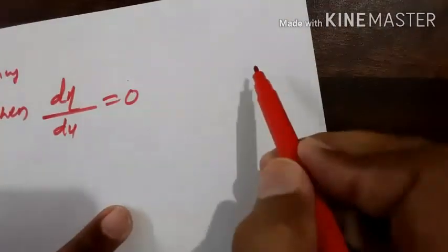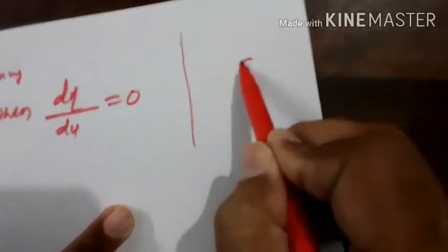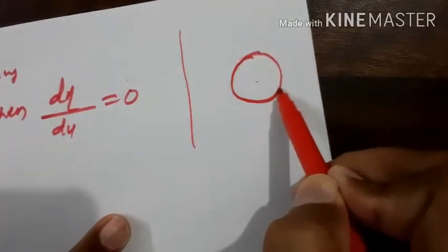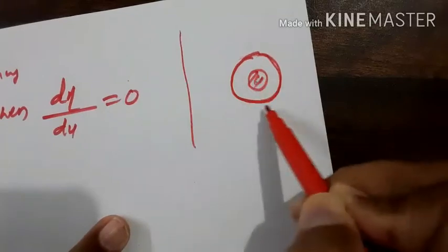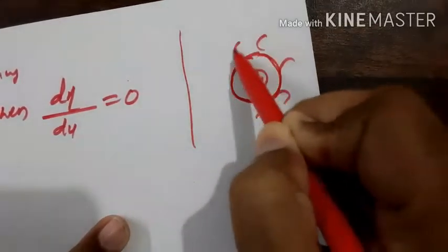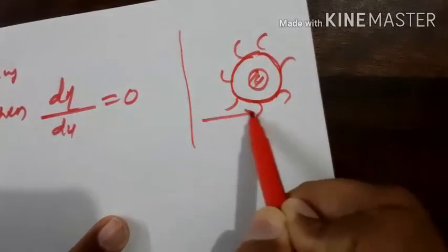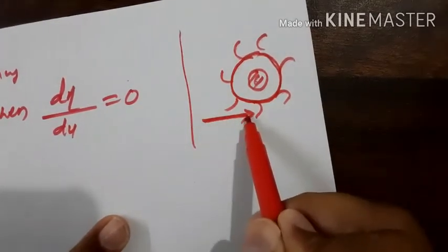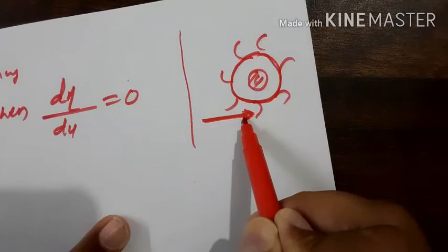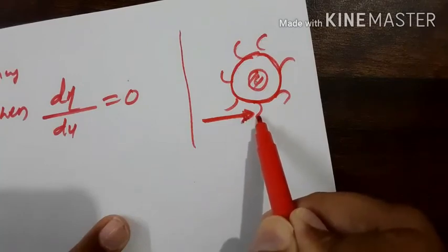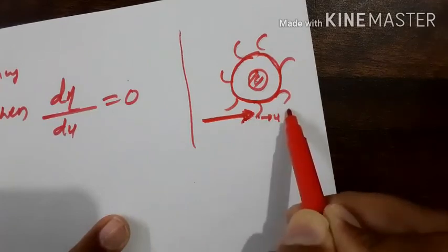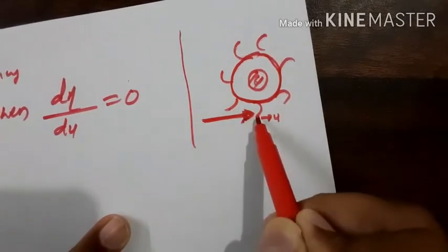Suppose you take a turbine. This is an impeller on a shaft, and the blades are mounted like this, and the jet will be striking. This is the input energy you are giving, the kinetic energy of the jet. The jet strikes the blade, and the blade starts moving with a velocity u. It moves forward, then the next blade comes and stands before the jet.